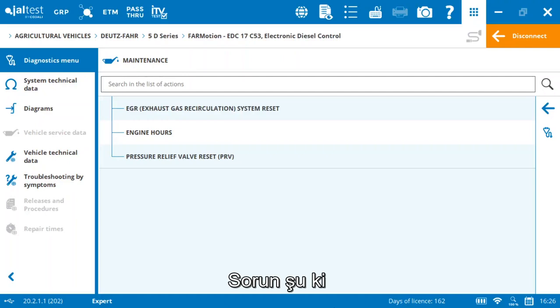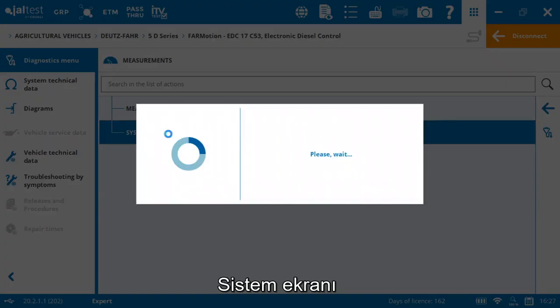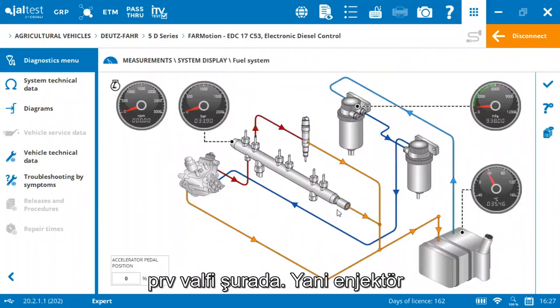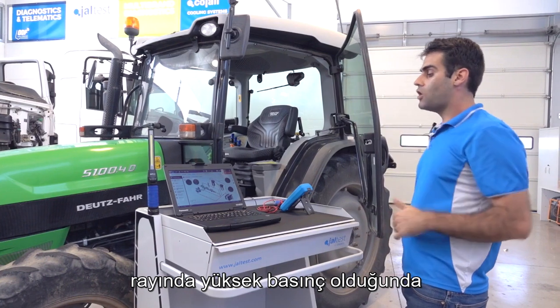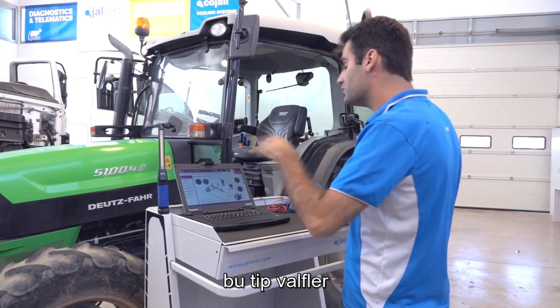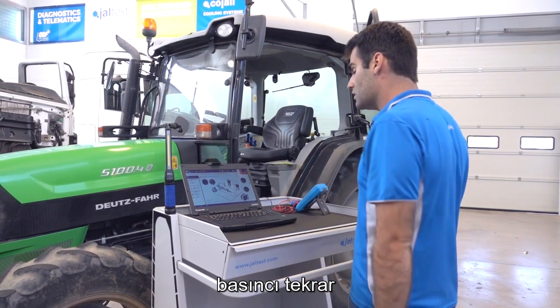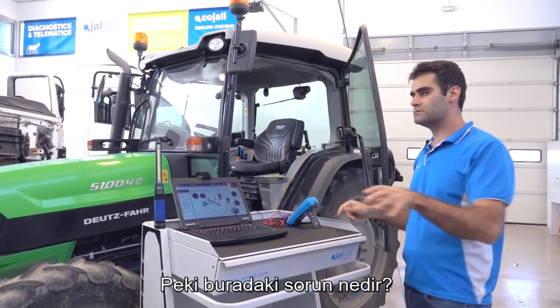I'm also going to use the system display to see better what I'm talking about. In the system display, the PRV valve is this one here. So when we've got high pressure, over pressure in the injector rail, this type of valve will relieve the pressure again to the low pressure side of the fuel injection system. But what's the problem here?